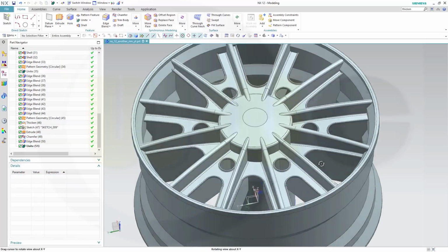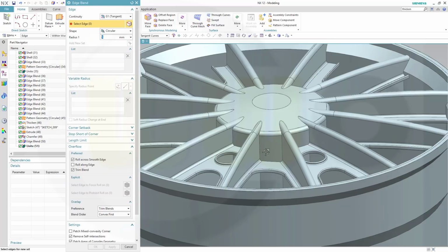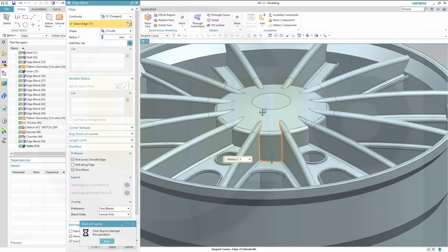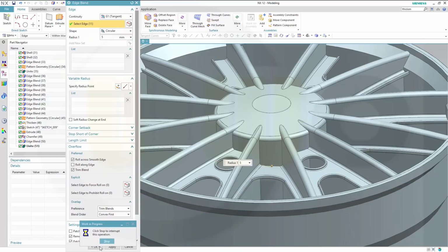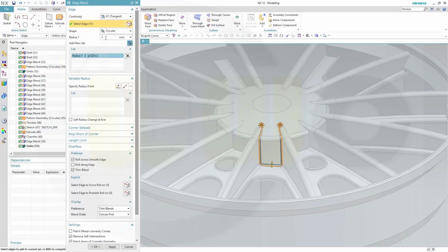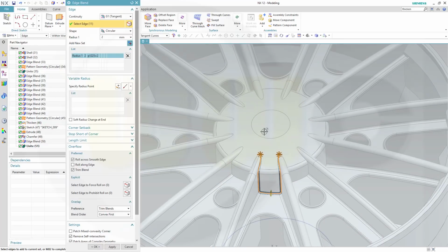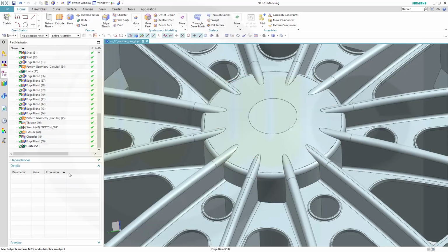Yeah. Let's try another fillet here. Go for edge blend, select. Let's see how it goes around. Oh, it does. Blend faces overlap, that's okay, no problem here. So confirm this one, see if it works. No, doesn't. The preview is okay, but it doesn't work, so let's go for 2. Yeah, and that it will not go around. So cancel this and change that one.